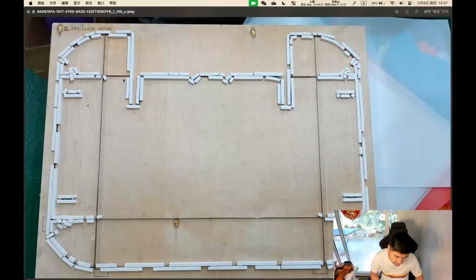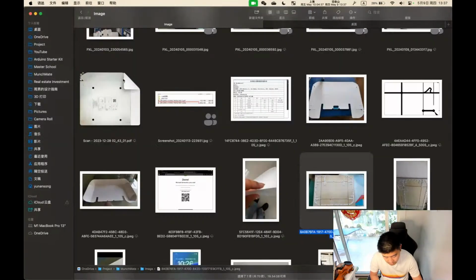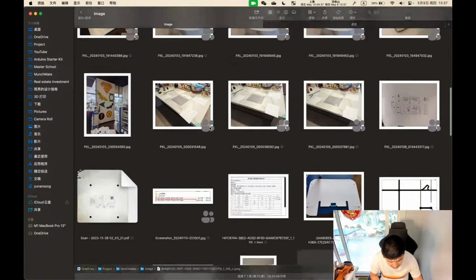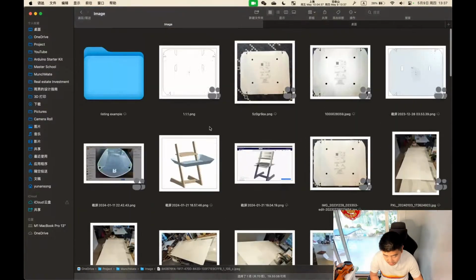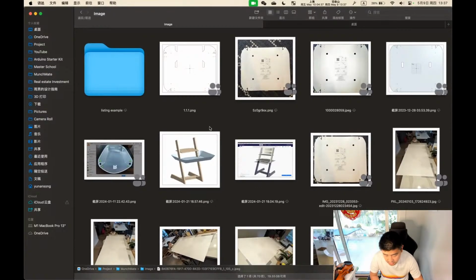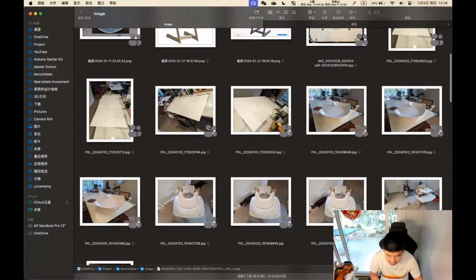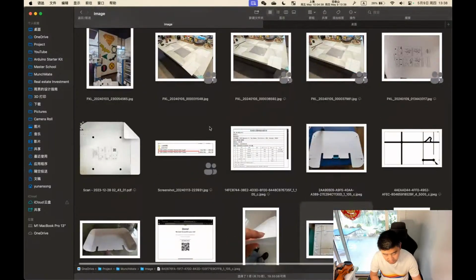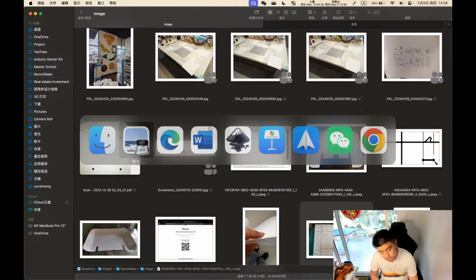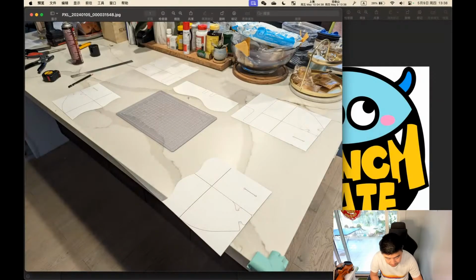So you can laser cut, you can CNC, but that's going to be slow and costly in runtime. So this is why you make a tool, but the trick is you have to freeze the design and finish your design. If you make any change to the design, that means you have to update the tool, which sometimes can be very expensive, right? In this case, not that bad.